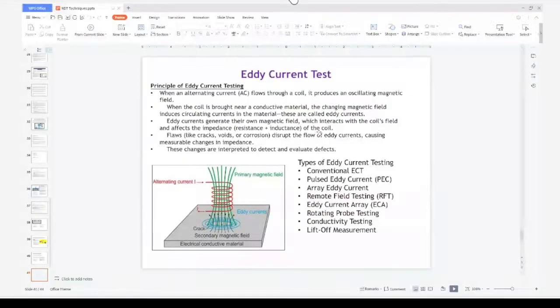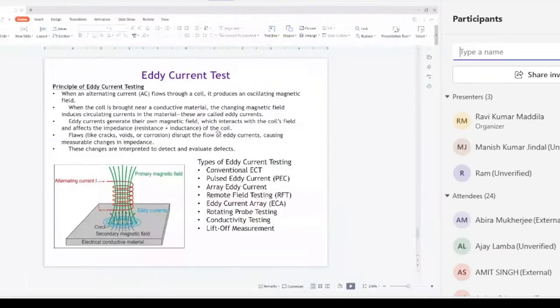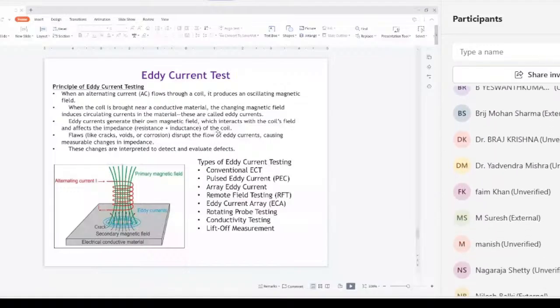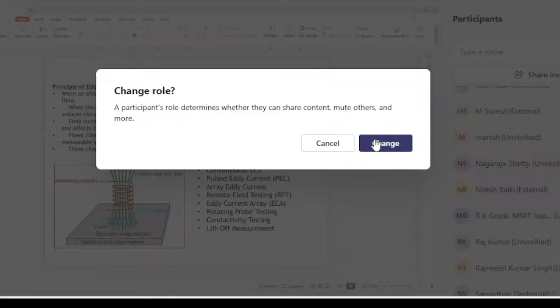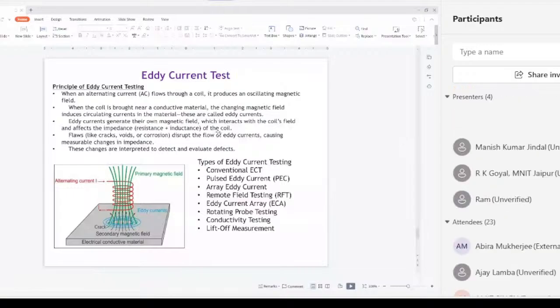Another novel technique which is recently popping up in the NDT area is terahertz imaging. Like electromagnetic waves, the frequency is much higher than the ultrasound range. So in the terahertz range, non-ionizing waves are used to inspect the part. It's a rapidly emerging technology, especially in the composite industries. Currently it is used in the medical field and in the pharmaceutical and semiconductor areas. The idea here is that these terahertz rays are passed inside, like an ultrasound.